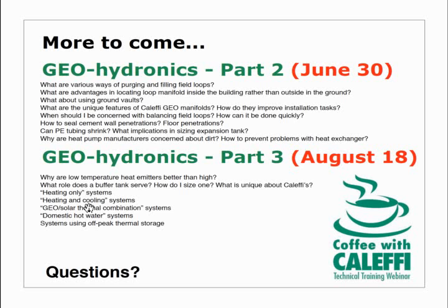And there are controls on the market, and more coming, that can measure humidity and temperature and calculate the temperature that the surface would need to reach to form condensation. And then it's simply a matter of keeping that surface 2 or 3 degrees above the dew point to prevent condensation. And the moisture removal has got to be done through a separate air handler or some other device where condensation can form and be collected without damaging the surface. But I definitely see radiant cooling and geothermal water-to-water heat pumps as a growing market.